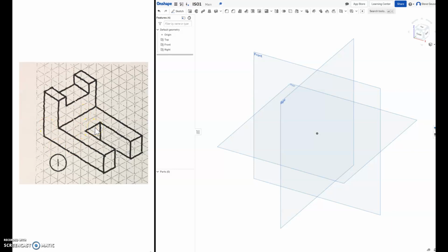The basics for beginning to draw a part is that you're going to want to start by looking to see if the part has more or less one shape that we can draw. Look at the front face, and this is the front face that we're going to want to draw. So we draw this shape, and you don't have to necessarily draw it to dimensions first. You can just sketch it and then dimension after, and that's the technique I'm going to recommend. So we're going to start always drawing the front face on the front face.